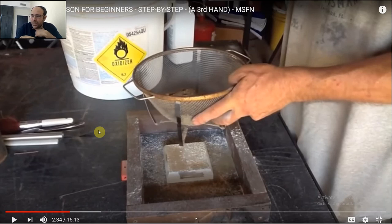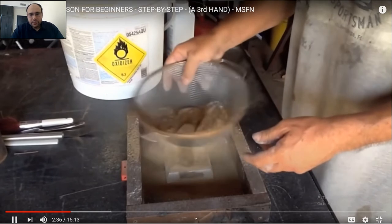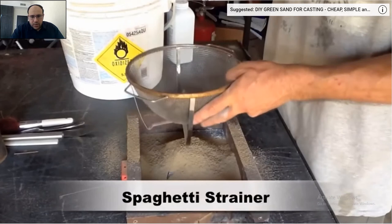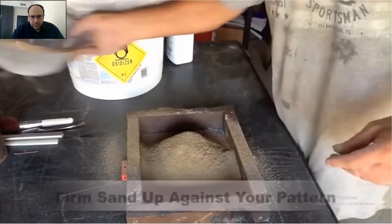So what he is doing now is another process, known as mold making. We started by making the pattern. This is step one. And the second step is to make the mold. Making the mold requires a procedure by itself, as he's doing here. And now I'm going to put on some facing sand, and that needs to be sifted so you get a nice surface finish on the casting. And that only needs to be done on the pattern itself.